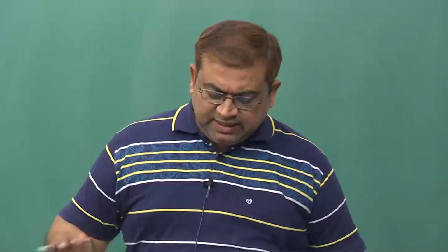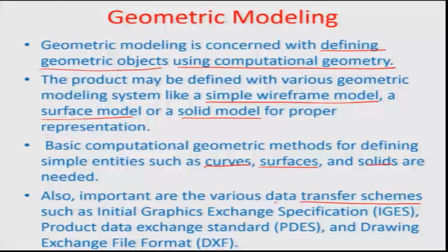For that there are certain exchange and transfer schemes which have been set up internationally, and people designing CAD platforms generally follow such schemes. One of them is, for example, the Initial Graphics Exchange Specification IGES, or the Product Data Exchange Standard PDES, or the Drawing Exchange Format DXF. Most of this you use in your normal methodologies while handling CAD.